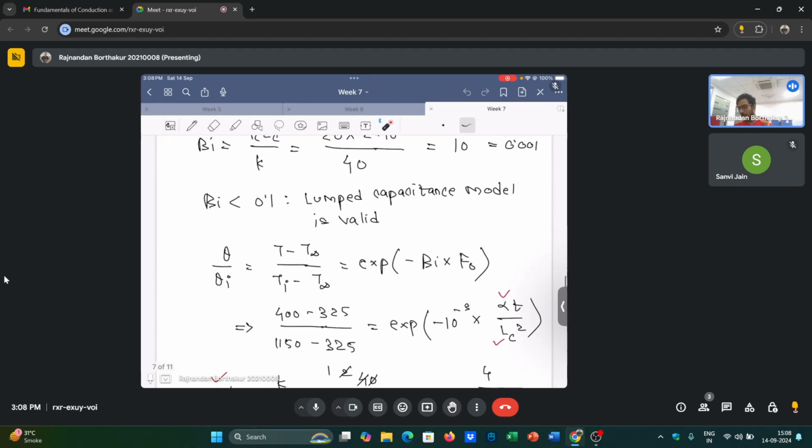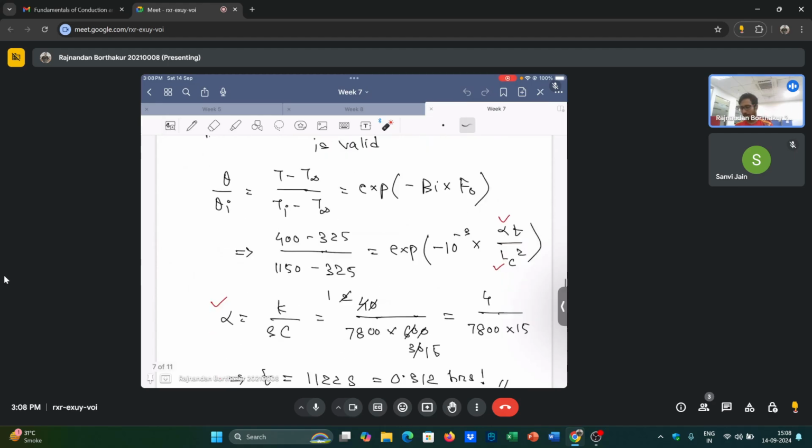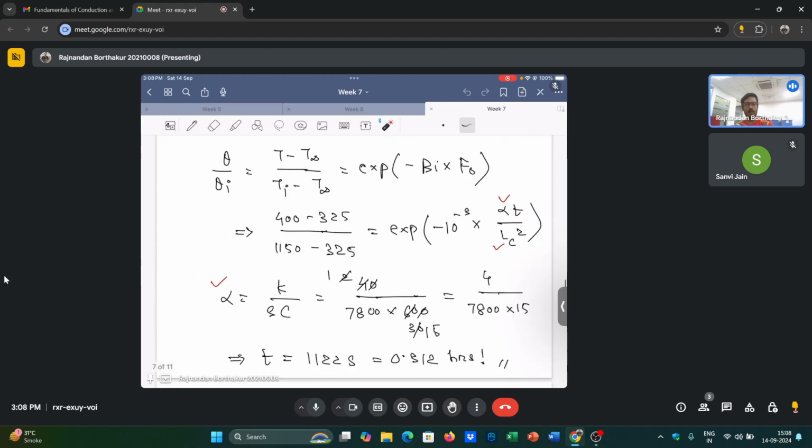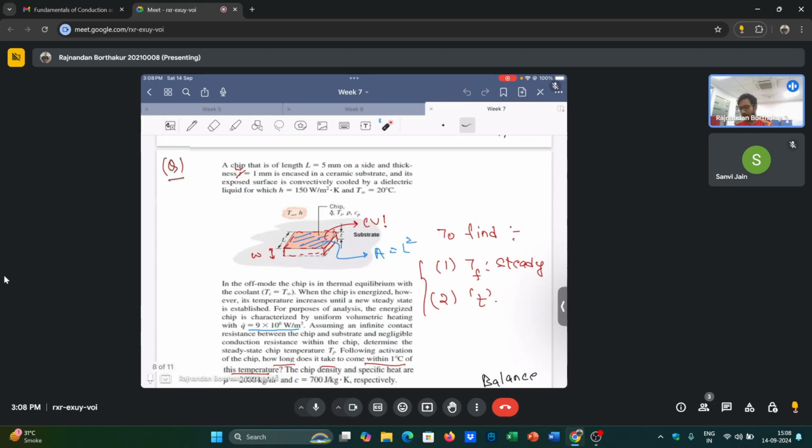And then we simply use the expression for the lump capacitance analysis to calculate the time required to cool the balls. However, in one of the next problems, we saw that even though we can assume an object to be a lumped object, using directly the expression of the temperature, which is exponentially decaying with time, can sometimes lead to wrong results, because in this case we established this numerical because of that.